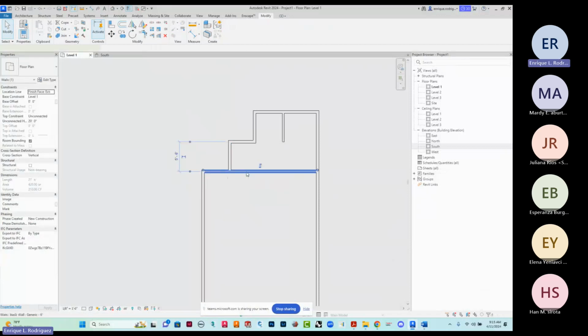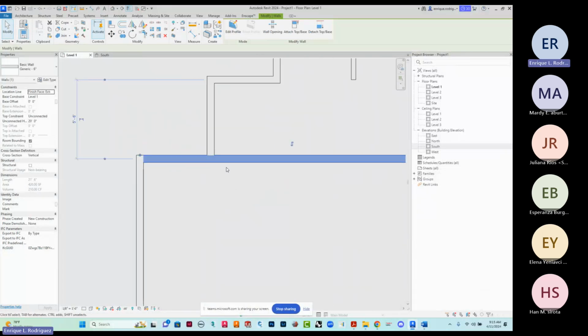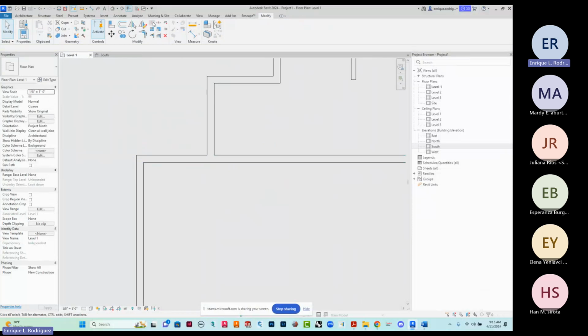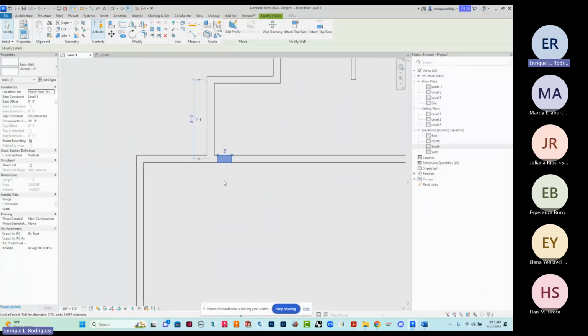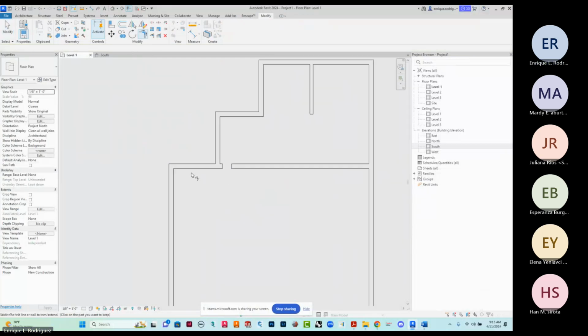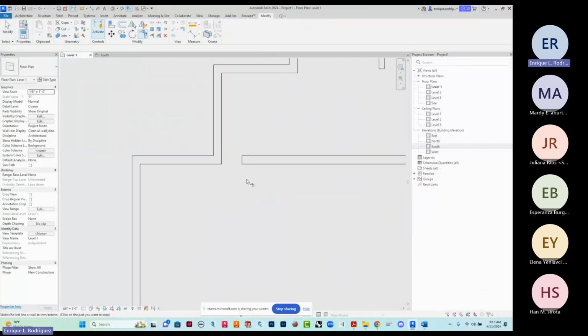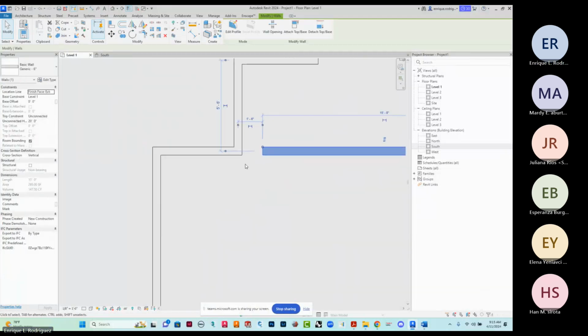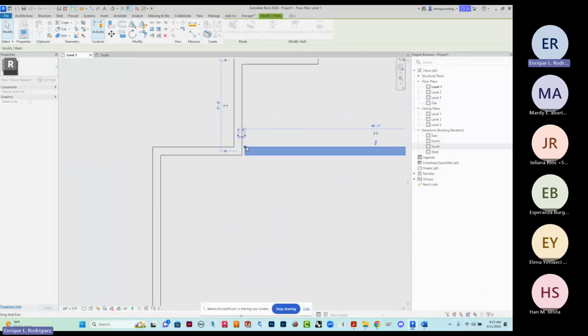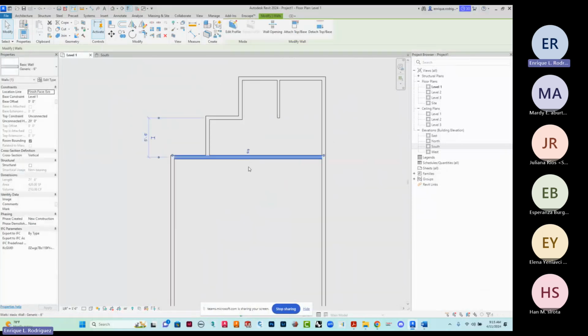So what we need to do is break this wall. And this is what I do in most cases. I will go to this split element command up in here, and I can start here, and I'm just going to delete this. And I'm going to refill it with this. And here's part of the problem. If I was just to bring this all the way to here, let's do that correctly. It wants to join the wall again. Okay. So I'm going to undo that.